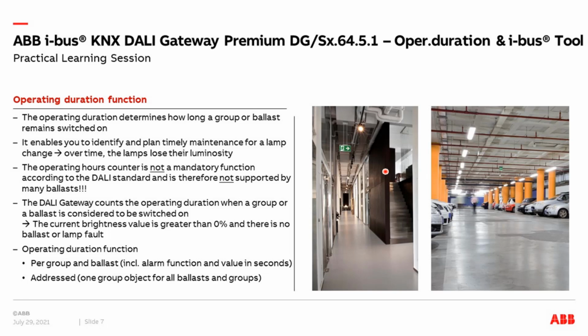But very important, we must know the operating hours from our ballast. According to the DALI standard, the operating counter function of a DALI ballast is not mandatory. There may be some ballasts on the market that support this function, but it's not mandatory. And so a wide range of ballasts don't support this function to count the operating hours. That's why we use the following solution in our DALI gateways. Now we count the operating duration when a group or ballast is considered to be switched on. What does it mean?